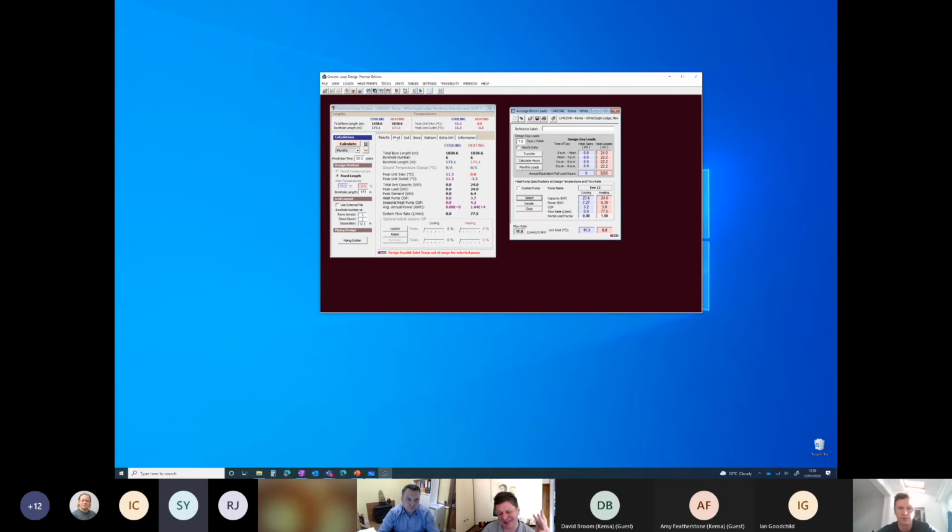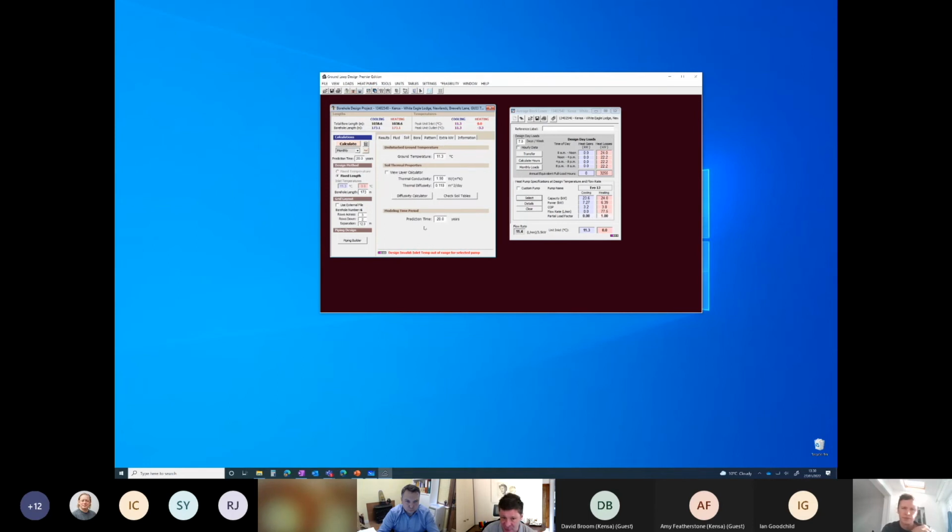So it's not a particularly friendly piece of software, but it's very utilitarian kind of. You tell it about the fluid, so ethylene glycol. You tell it about the soil conditions, and this is where the geology all gets inputted: temperature, conductivity and diffusivity, as I mentioned earlier. We then give it the characteristics of the borehole. So is it a single U-tube, a double U-tube, is it coaxial? Is there a pipe being pushed to the outside of the borehole? What diameter the pipe is? What the flow in that pipe is?